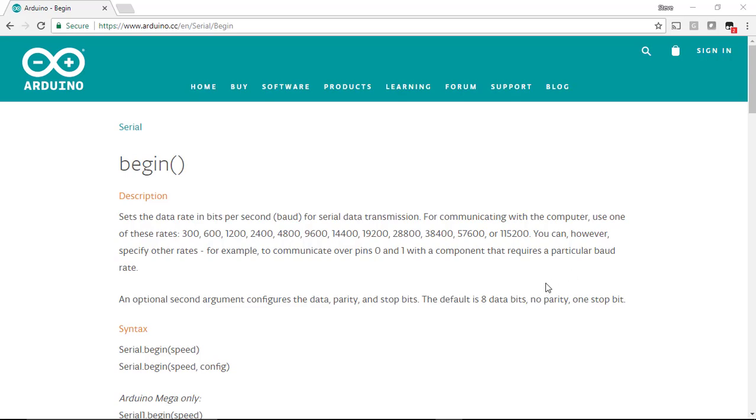And also interesting to note here that pins 0 to 1 on your Arduino, if you take a look at your Arduino Uno board, these pins are designated for serial communications. So you'll see on your Arduino that pin 1 is designated for transmission and pin 0 is designated for the receive. So TX and RX are serial communications on your board pins 0 and 1.